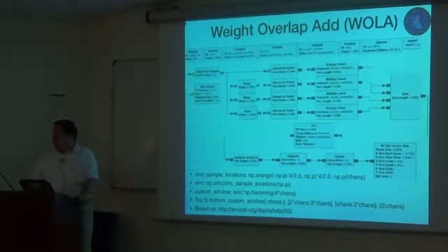All of that is possible and certainly interesting, but at the moment, this I can just click together, like I said, and this is specifically using only 5 megahertz of our spectrum. It would be really nice to take the whole spectrum, and then we're starting to move away from the hardware-based backend towards backends that possibly support RFNoC even, and so we could do much of the heavy lifting in the FPGA before we even get out of the chip.